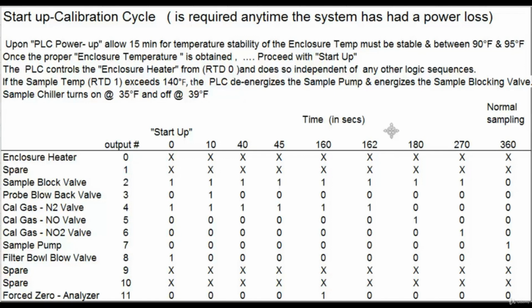Murphy's Law says anything that can happen will happen. And in the world of process and automation, that's very true. If it's possible for somebody to throw a shoe into your water tank, it will happen. And when that shoe blocks your discharge valve, what is your PLC going to do about it? You have to think about not only how is the machine designed, how is the machine supposed to run, but what things can happen along the way, and how are we going to handle those exceptions.